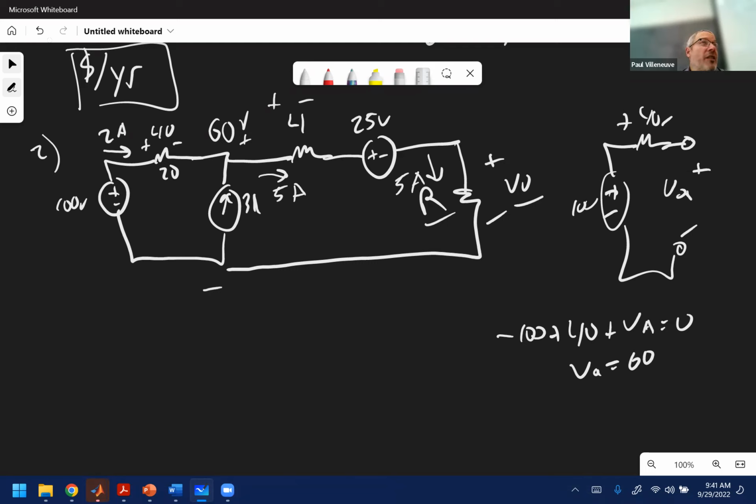You just have a lot of auxiliaries. So you might have to provide power to the batteries, the lights on whatever you're pulling. You might want to plug something into the cigarette lighter and have additional lights. So it just gives you that extra capacity so that you can tow whatever you need to. So that would be a heavy duty alternator or heavy duty charger. But you still don't need to upsize the battery. As long as the battery is able to start the vehicle over the next 6 years, then that's all you need.